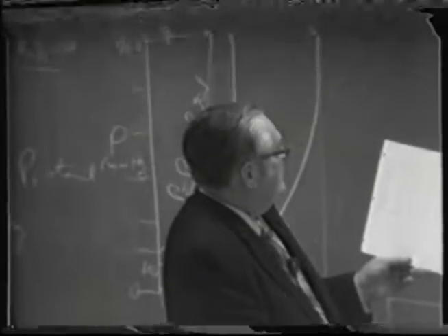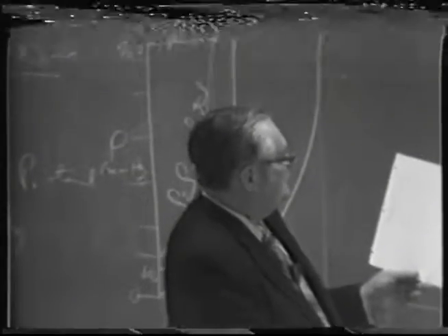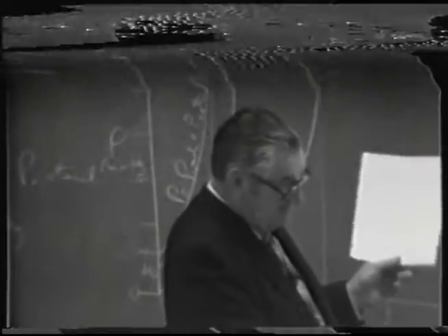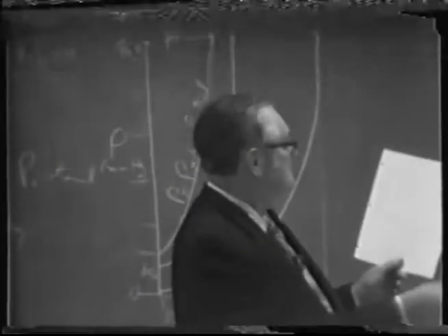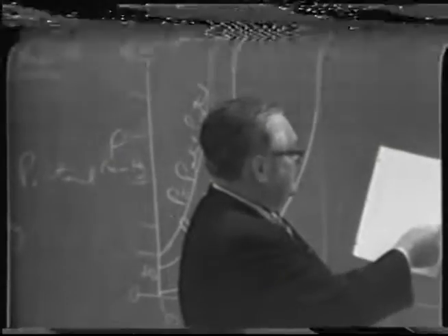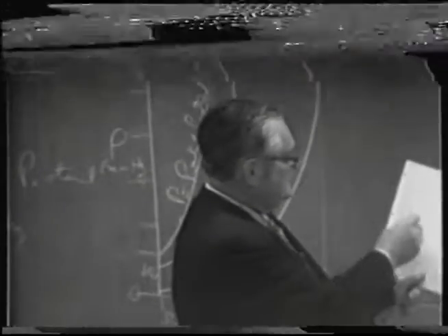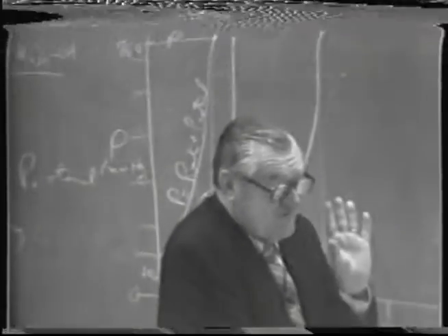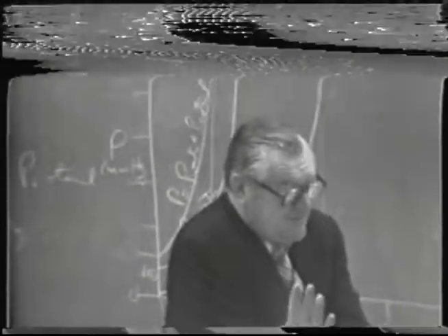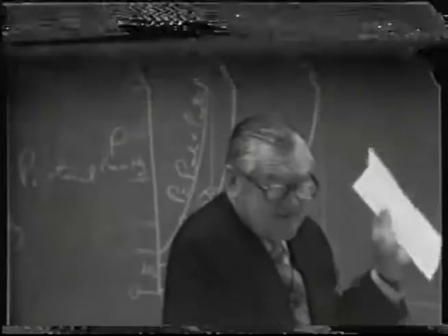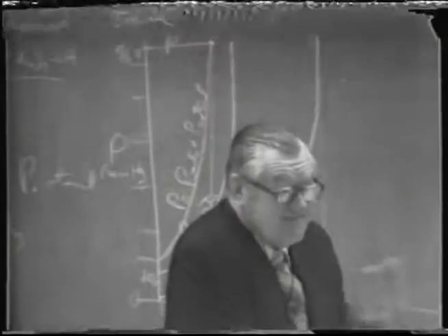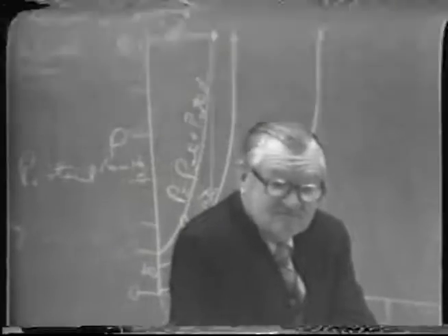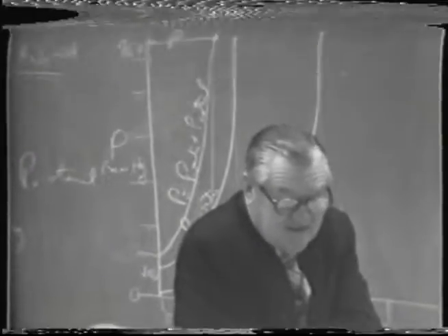And then you get into isobutanol and normal butanol, where you have the appearance of two liquid phases, or in other words, a heterogeneous azeotrope. And you can go on down through there, and so there's really no sharp demarcation line between the four systems that I've discussed. That's the one point I wanted to make by this table when I give it to you tomorrow. But you progress sort of gradually as you increase the molecular weight of a homologous series of substances like alcohols.